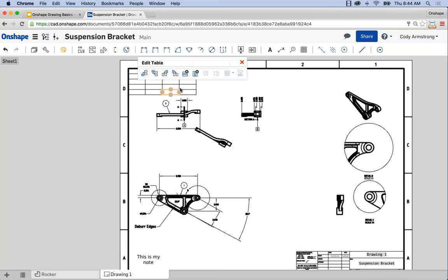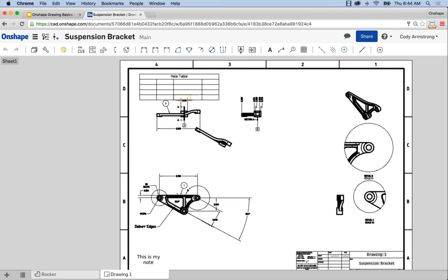Some bits about the table, you may have seen it there, but if I left-click a cell or a series of cells, if I window select, for instance, or if I command-shift a whole bunch of cells, you'll see that I can tweak the table, I can edit or remove columns, I can merge cells if I have several cells selected. So you do have some table editing functionality in there as well. You can change the table up a bit, add or remove cells and columns and so on. But that is the general purpose table. You'll see it here in the far right. Again, to place it, you have to define the size, then left-click the top left corner, and then the bottom right corner. Okay.